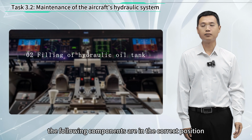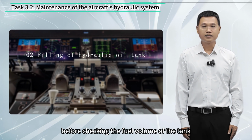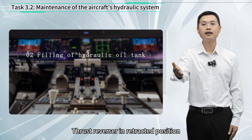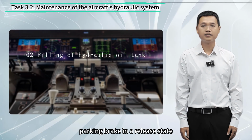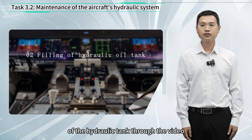Make sure the following components are in the correct position before checking the oil volume of the tank. Spoiler in lowered position. Landing gear in the lowered position. The landing gear door is closed. Thrust reverser in retracted position. Brake accumulator in supercharged state. Parking brake in a release state. Let's learn about the filling operation procedures of the hydraulic tank through the video.